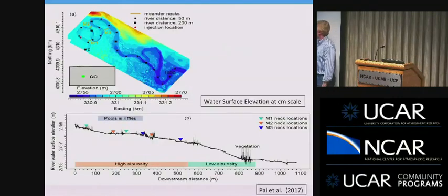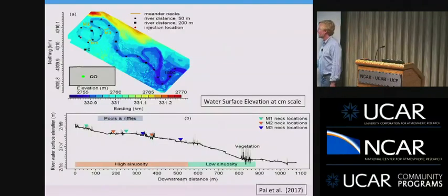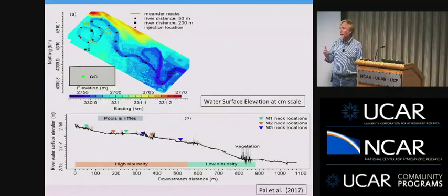And what we can then do is estimate the hydraulic gradient across each one of these meander bends. We know something about the hydraulic conductivity. We can calculate the flux through these. And it turns out, not surprisingly, the fluid flux through any given one meander is probably about 0.01% of the total stream flow. Hardly anything. But it is important biologically, and if you add that up for a meandering stream that might have several hundred meanders in it, it begins to be an important exchange phenomenon. And we can now quantify it because we have the hydraulic gradient quite easily calculated.